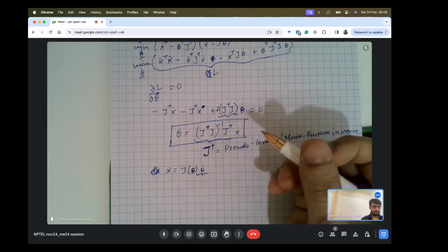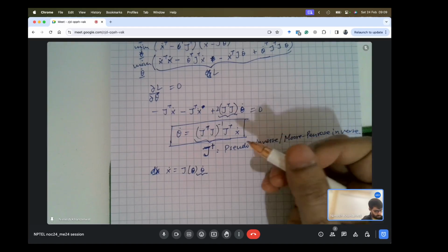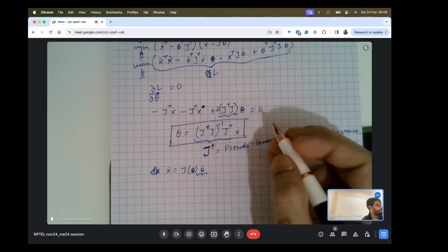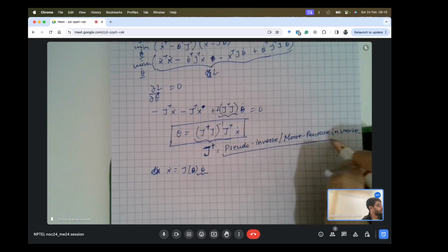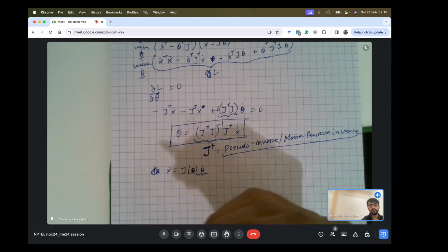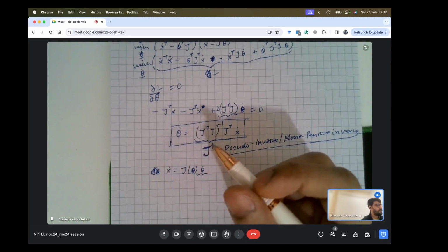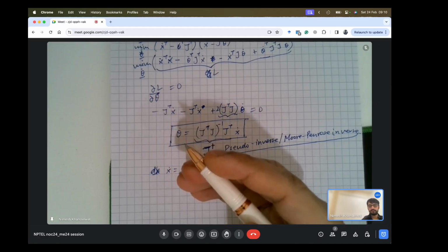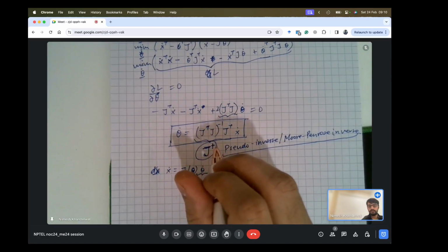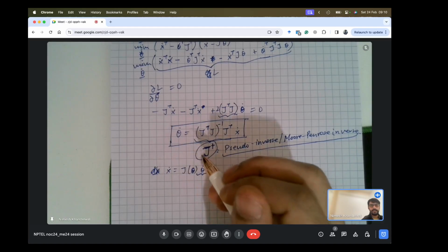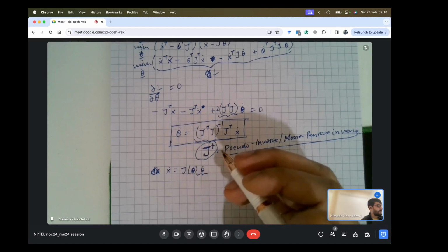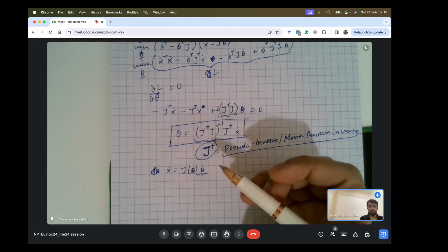And now, if we delve a bit deeper, we can say that when we are taking the pseudo inverse, we are partitioning the total space into two different spaces: one defined by the column space of the pseudo inverse, and one defined by the null space of J. So what do we mean by that?